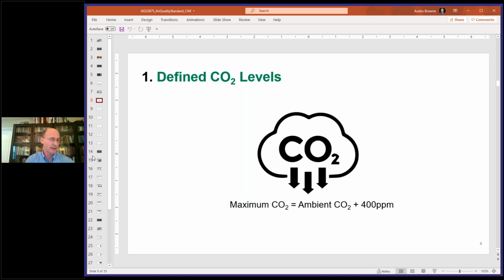And then, thanks to the IH interface with this committee, we came up with 2500 ppm, which is the action level for CO2, as the second alarm level. That's the absolute alarm. That's when you've got to take action. So that's one interesting aspect of the standard, which is unique, having the two alarms and the ability to adjust those alarms, at least the first alarm, based upon site conditions. Next slide.